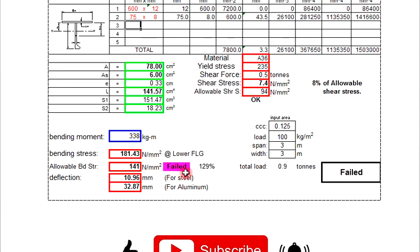Okay, so this one will become fail because it has the 100 kilogram per meter square. Unless you want to change the load, because the total load based on the size of the plate, let's say span 3 meter and the width is 3 meter, total carry is 0.9 ton. Okay, 0.9 ton.